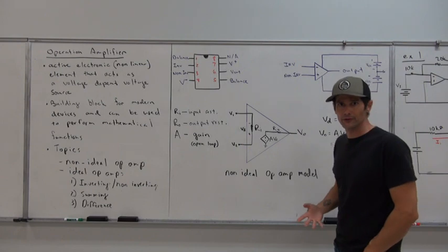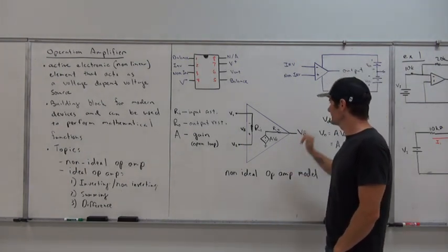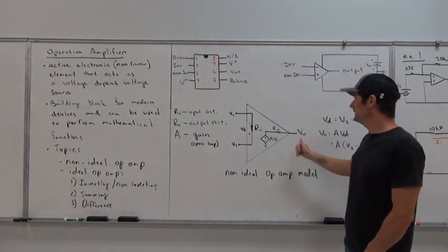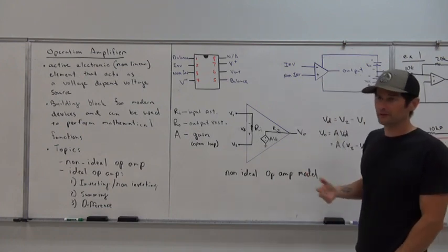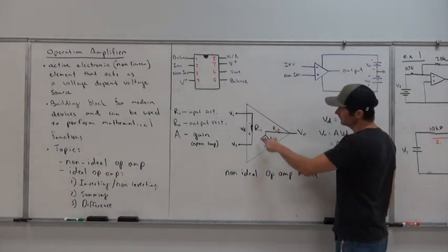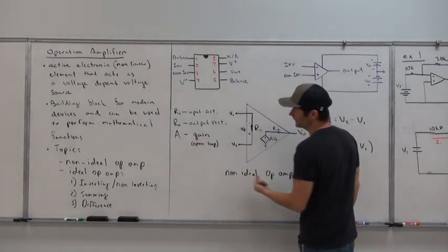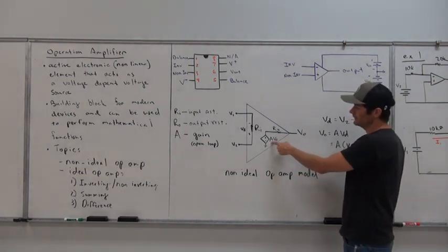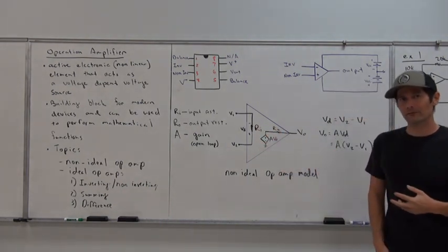When we look at connections of a circuit connected to the output or either of these two inputs, we can rewrite the schematic so that we can usually solve it with nodal analysis. Much of the time what we're concerned about is the gain, or what we call the open loop gain, between V0 and what we consider our input, Vs. Here, A is our open loop gain, and that open loop gain takes VD and multiplies it by that value.